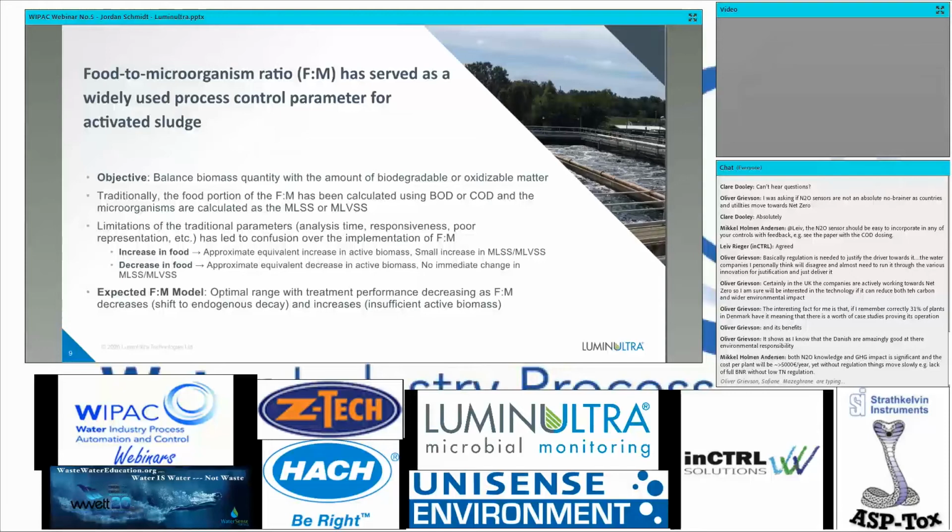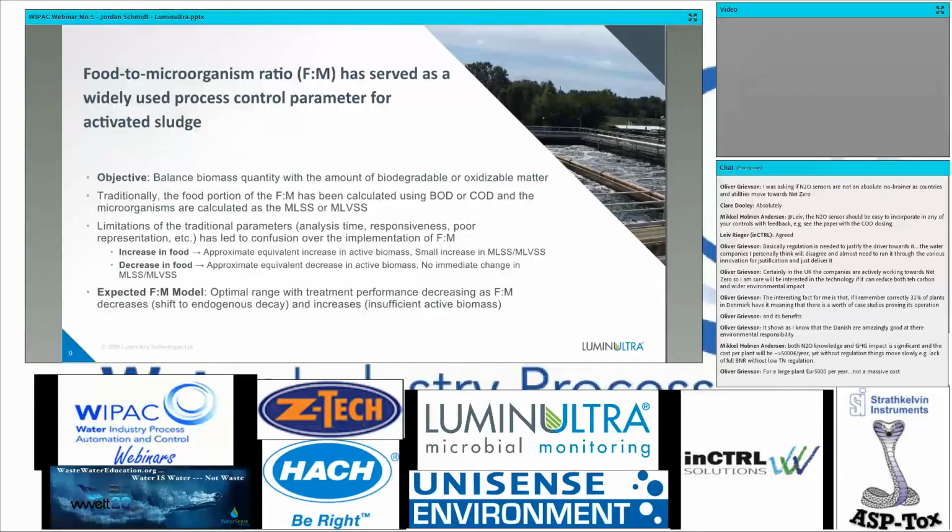These do have limitations, specifically analysis time. For BOD, you're looking at 5 to 7 days, depending on how you're measuring it. MLSS might be overnight. That really restricts your ability to use it as a rapid process indicator and make real-time changes. There's also responsiveness.